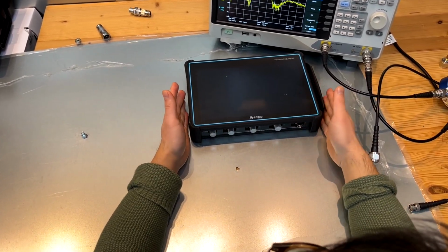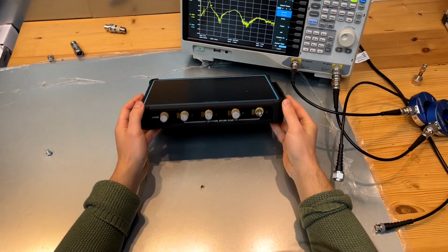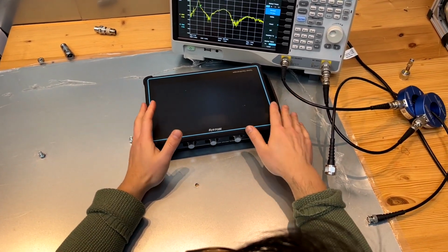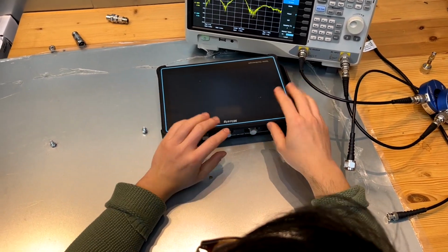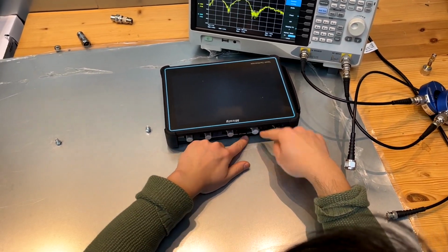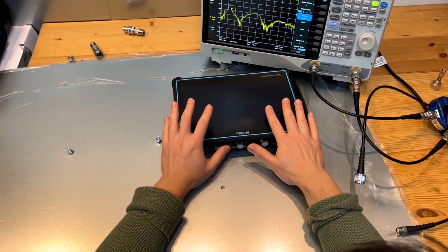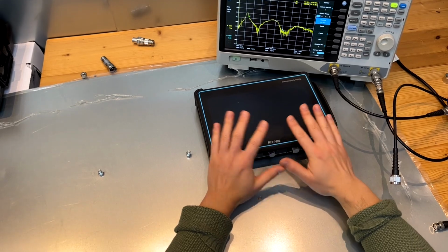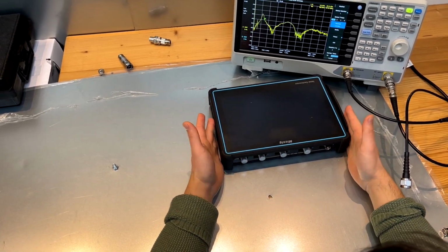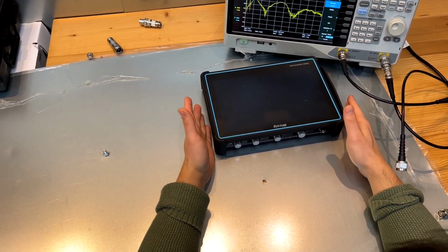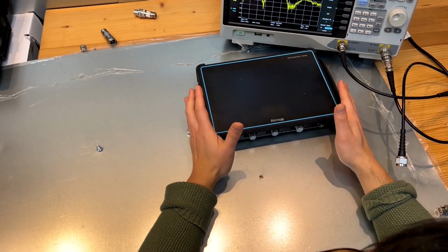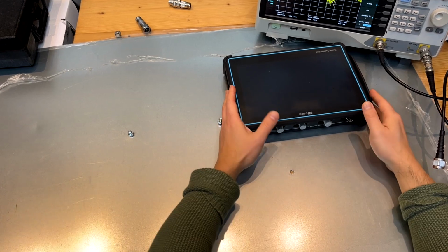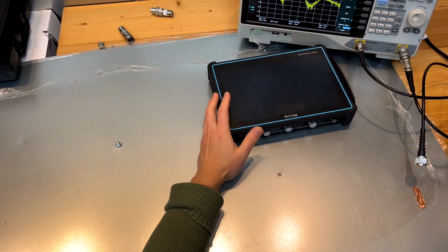And this thing, in this case plastic, just lies on this common ground. So most of the coupling would be by parasitic capacitance between whatever circuitry is in this oscilloscope and this common ground. But often if you have a metal enclosure, you can bond the enclosure directly to a common ground. That's even better to achieve a very low impedance bonding to this common ground. So now let's have a look.